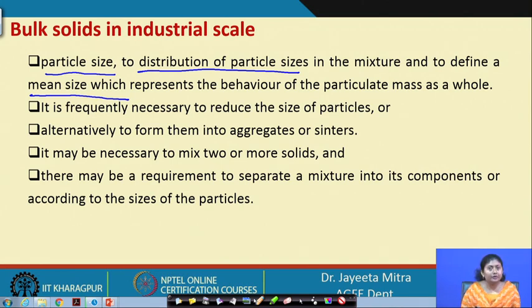They will not form a clump or agglomerate, and they will dissolve uniformly. So, in instantization, after spray drying we also carry out a certain kind of size-increasing operation, or a little bit of lump formation, so that the optimized size that we want can be produced. Those are the different operations that we need.